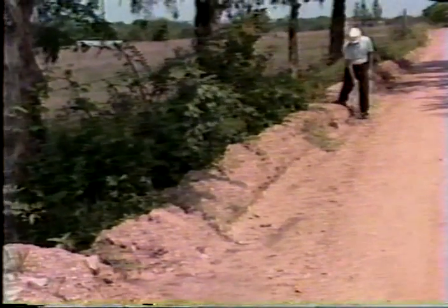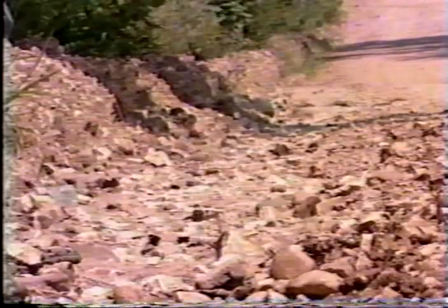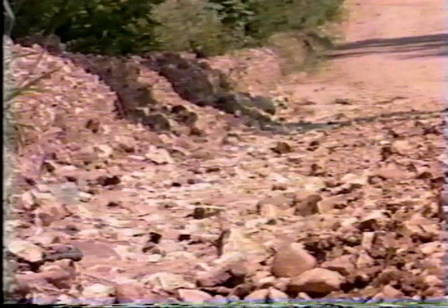Although not recommended, a windrow may be left at the side of the road. If windrows are left, cuts must be made at short intervals to allow runoff water to drain away from the surface of the roadway. Windrows left at the edge of the road act as curbs and can form secondary ditches, washing out low points in the road.